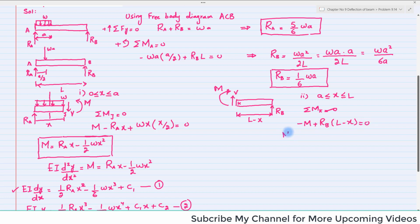So we have this reaction moment equal to RB into L minus x. Now this is the expression you will have to put in the equation EI d square y over dx square is equal to moment. Why? Because this is the equation which will be used to find the deflection and slope.